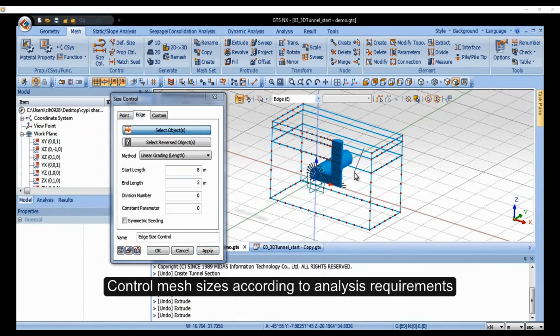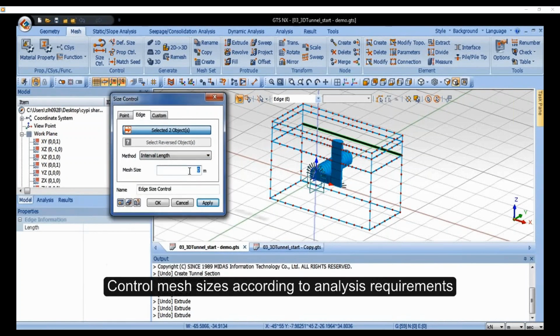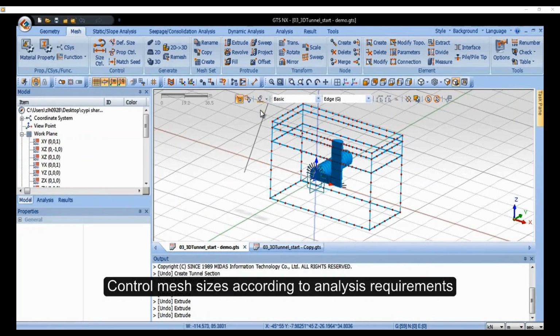We'll let the program then have that spacing, and I can do the inverse depending on which direction the arrow is pointing. I can also make it so that it's not just one single direction, but can be symmetrical, so I can say starting at one size and near the middle being a smaller size. So there are all these different options. I'm just showing you alternatives for controlling the size of the mesh around your model even before you start to mesh.